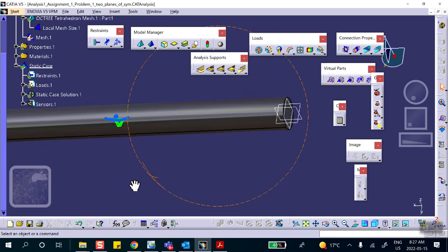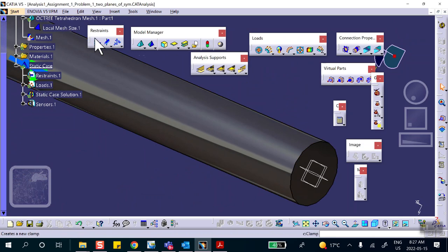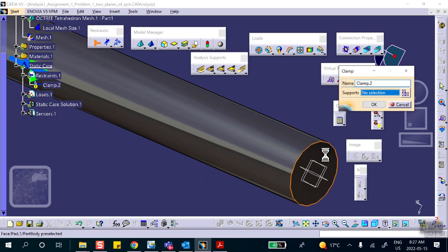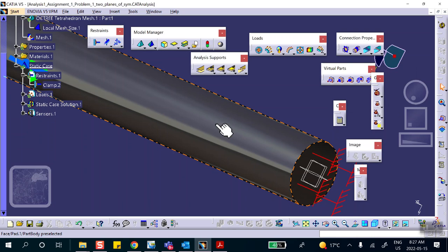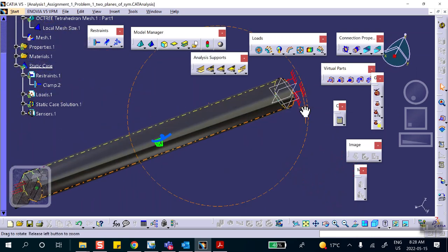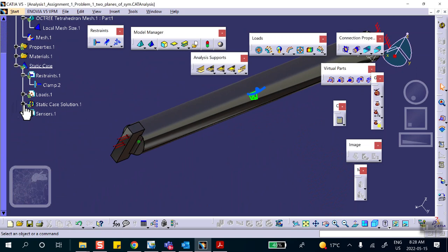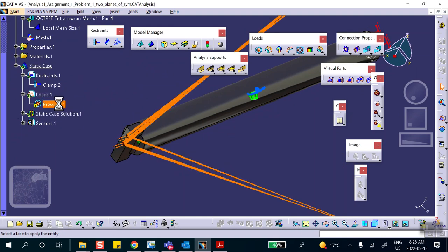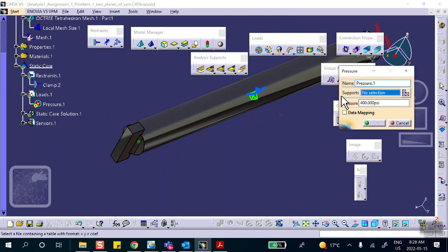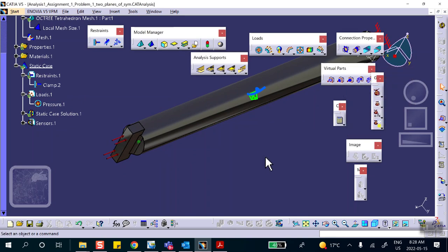We don't have any surface slider anymore, but we do have a clamp. This clamp at the right side. Okay, very good. And the pressure is okay, although there may be some issue because the surface has changed, but that's okay. The surface has no problem with it. It'll adjust by itself. Here, I select this. There. That error message that I got was the fact that, hey, you removed the surfaces, but the surface sliders are already there.